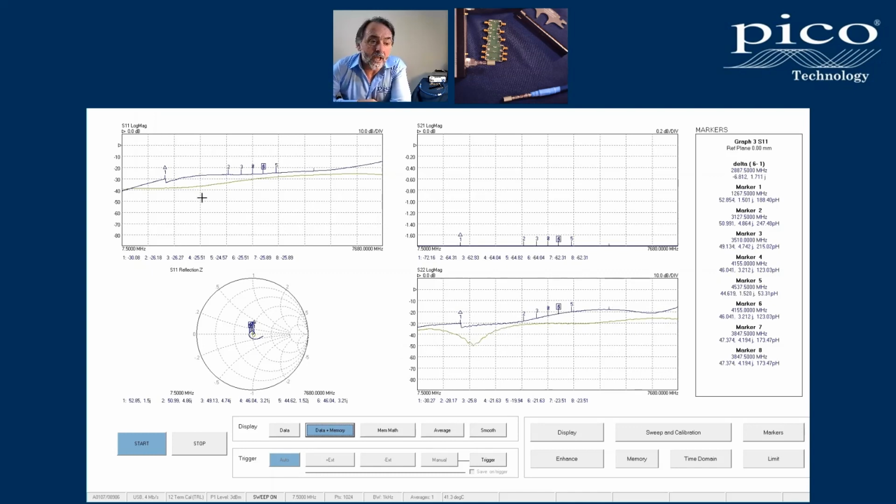They're all different calibrations, and the TRL and the TRM, so this is the TRM section, this is the TRL section, these two, the line and the resistors, do not quite match each other, and so we get this discontinuity here, and neither of them are exact matches for the 50 ohm, so we don't match that yellow trace there.